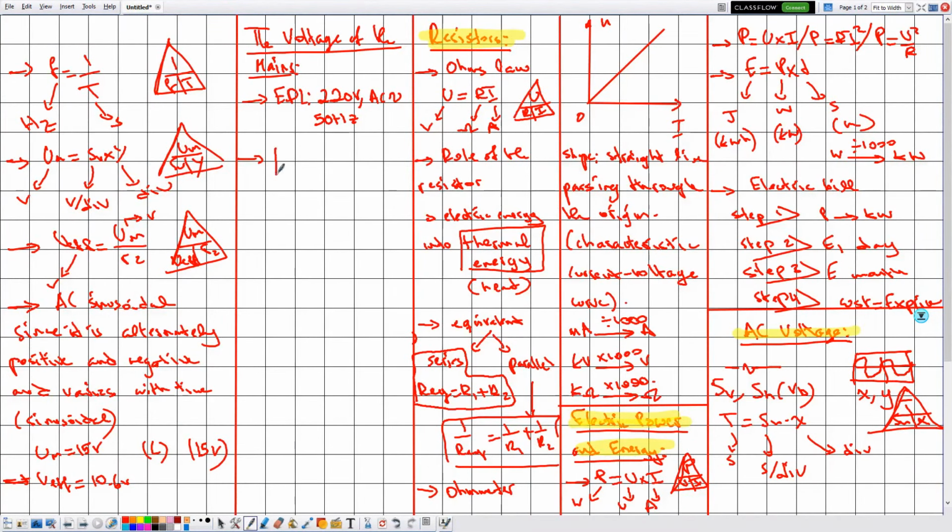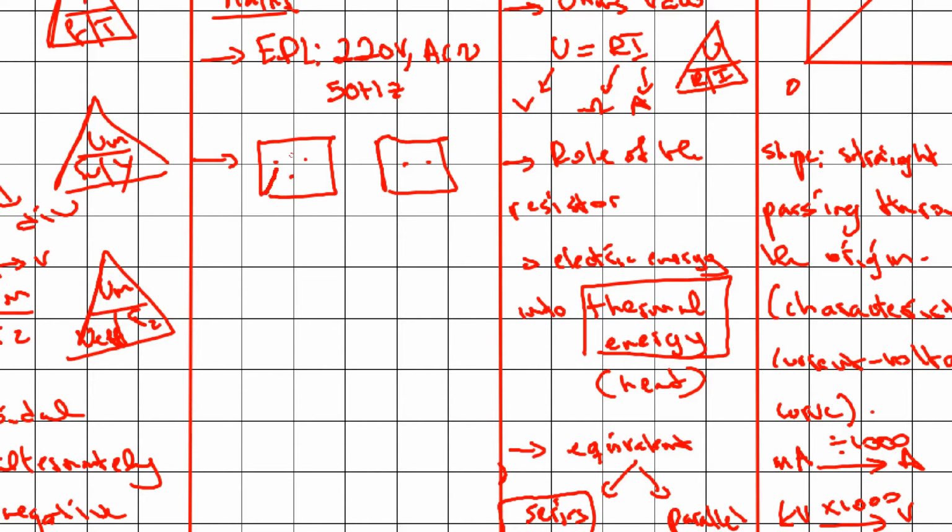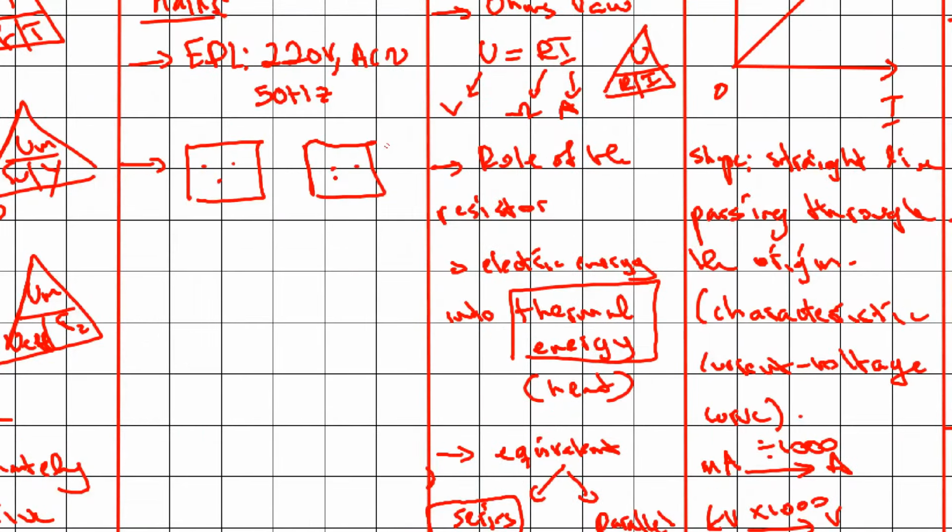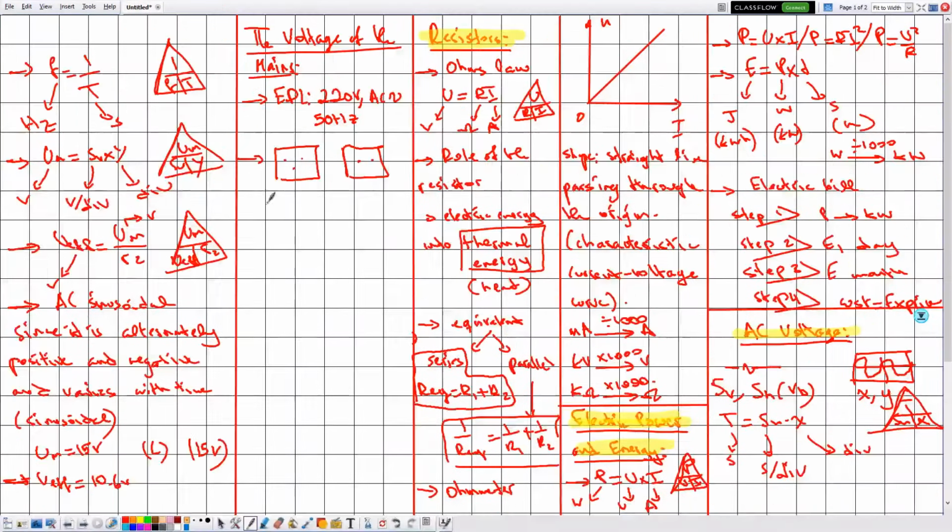Now the outlet consists of two types, either 3 terminals or 2 terminals. The one with 3 terminals consists of the live, the ground, and the neutral, whereas this one only consists of the live and the neutral. The live terminal is the one responsible for the variation in the voltage and for the electrocution. It can be distinguished using the live main indicator or the screwdriver tester.